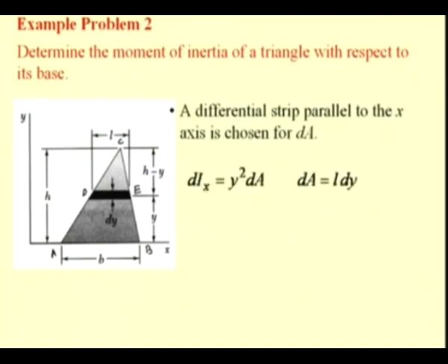So, these are the values. dIx is the second moment of this strip with respect to the x axis, which is y square dA, where dA is L times dy. Now, we have to determine this L.